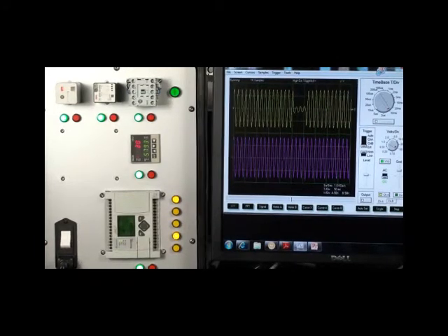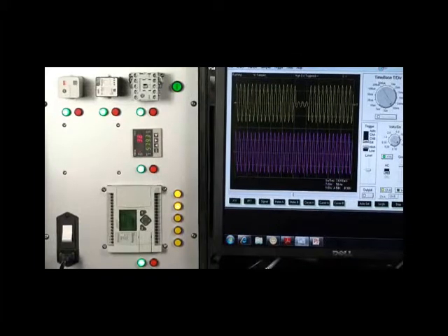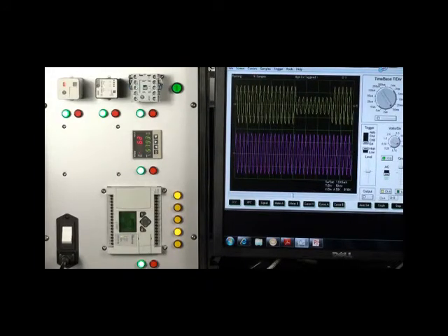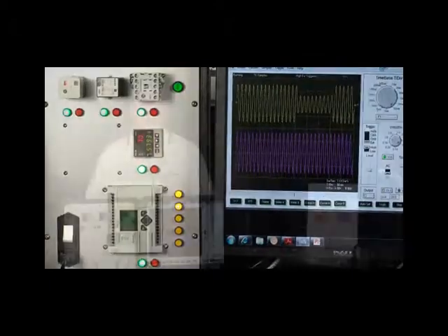Let's go ahead and create a couple others here. I'm going to change to 70 milliseconds and go back to one of our earlier events. Again, I don't have to reset anything, but just to again show a difference. Once again, I'm going to switch this up. We had an event that lasted 0.160 or 160 milliseconds long. In that case, it was at right around 50%. So we'll go up there and recreate that event. And once again, you can see the sine wave has been regenerated. The load is not seeing any difference from these voltage sags.